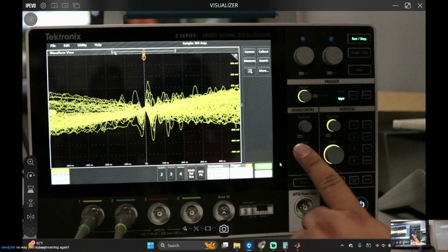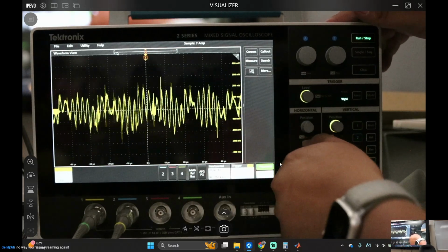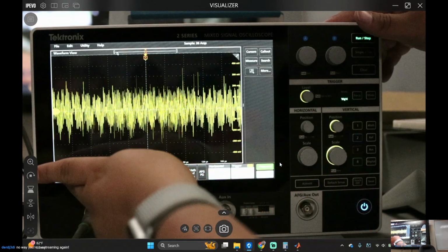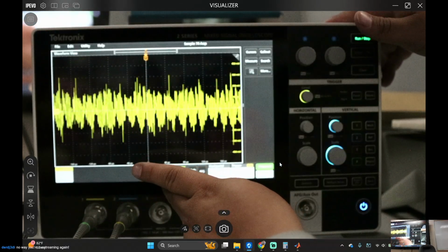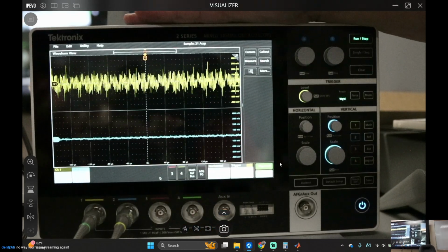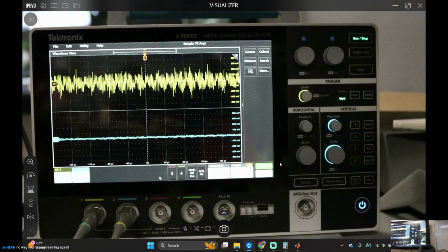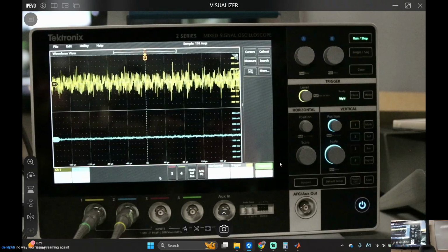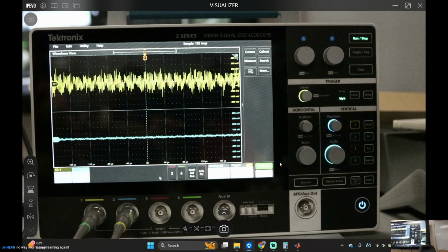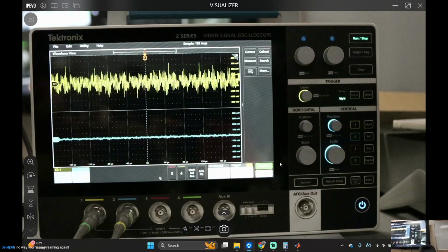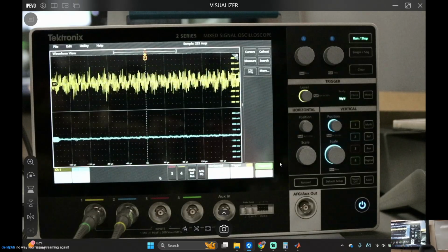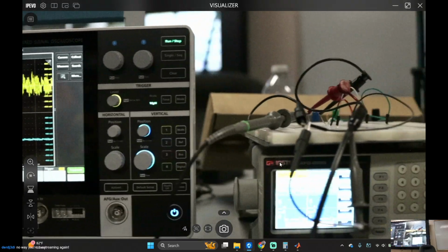Default setup, there we go. Okay, channel 1, channel 2. And this one, for just this lab, it might be a little weird with this oscilloscope. So what I'm going to do is set my waveform to a sine wave, my frequency, let's just leave that. Amplitude, let me show you what I'm trying to do.